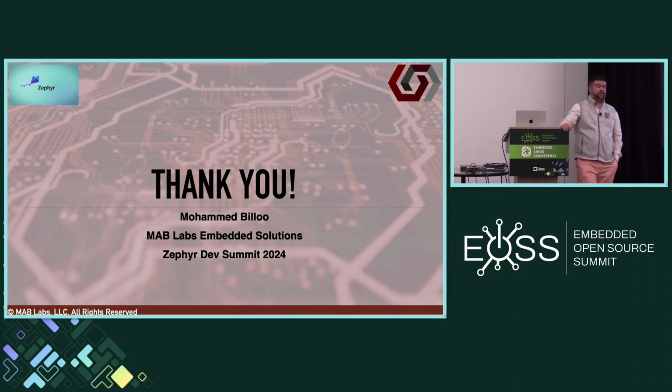Because the firmware is already there, resident on the flash. So U-Boot is just sitting there waiting, and then once Linux boots, the Zephyr side can send a message and get a message back to see if it successfully booted or not.